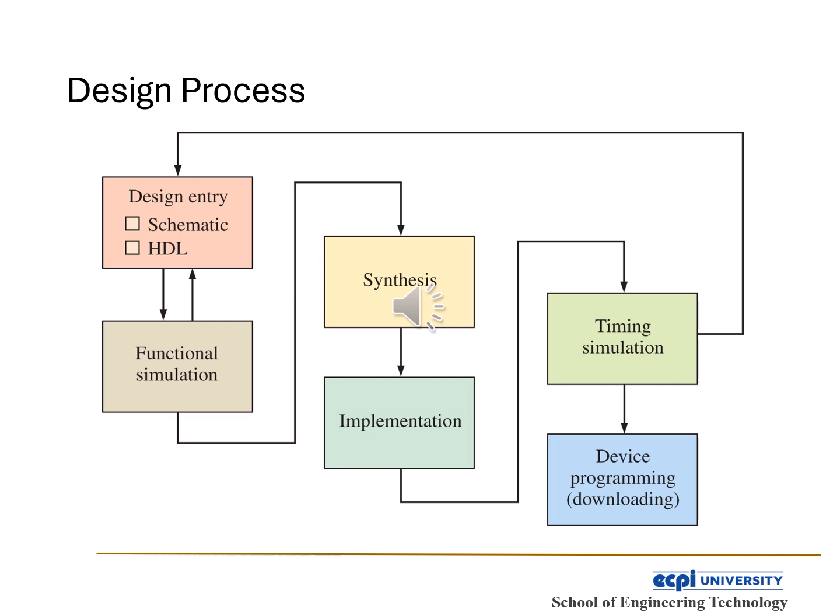Next, we verify it all with a timing simulation. This step checks whether your circuit will run fast enough and still function correctly in real time, just like making sure the plumbing and electricity won't overload the system. If that passes, then the final step is device programming. We load the design onto the FPGA chip itself. Your logic is now alive in silicon, ready to run, react, and compute. And just like that, your digital idea becomes real hardware.